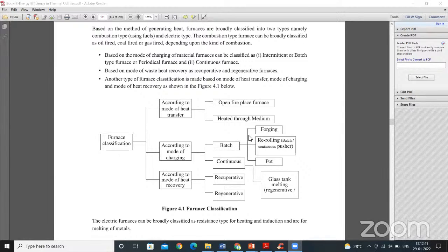For example, we recently went to one company where they are using a furnace, a metal melting furnace, melting a wear resistance cast iron, WR grade, and that is normally used for 2 shifts per day. They are sending the output material to the holding furnace, and from the holding furnace it is given to the machining center, because they are manufacturing extruded rod from the material. That is why it is used for only one shift or a maximum of 2 shifts per day.